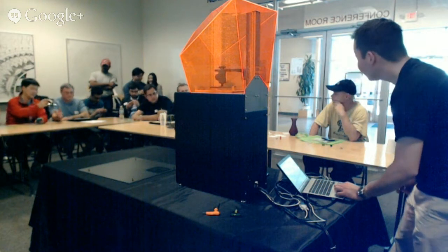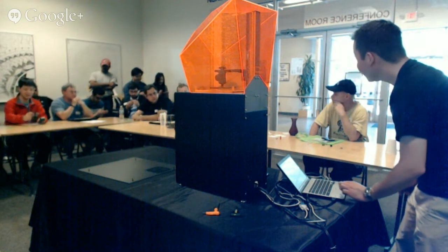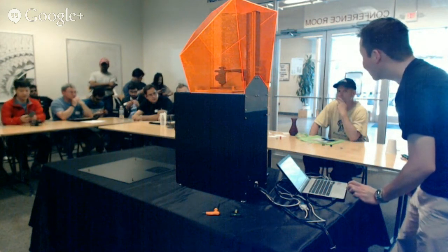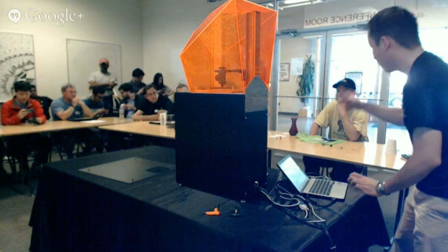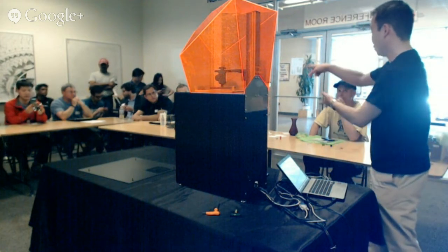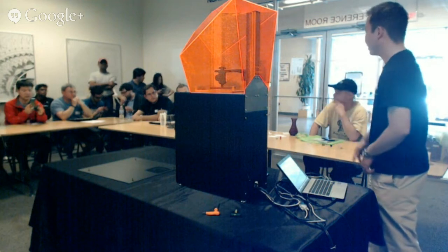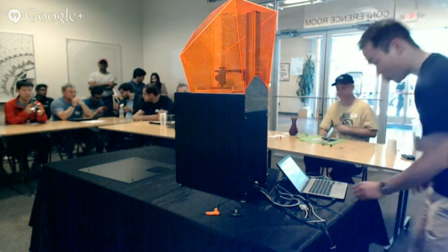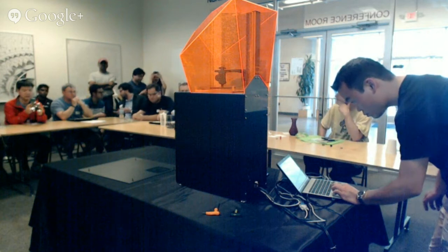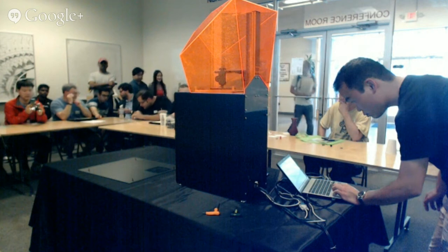John, so do I understand correctly, this is the original detailed resin, and then they did a silicone mold and then cast this? They printed with our resin, right? And then after that, they create a mold using vulcanization. So what you do is you buy these slabs of natural rubber, and then you clamp the piece in it, and you stick it in the oven, and then that will melt out cast.